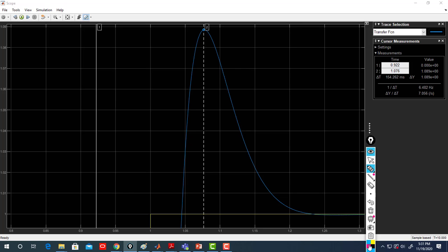Okay. No saturation block. First scenario. Then it has an overshoot amplitude of 1.089. Well, this is not the only criterion we could compare. We could also compare the transient time and so on. But let's just keep it this way.